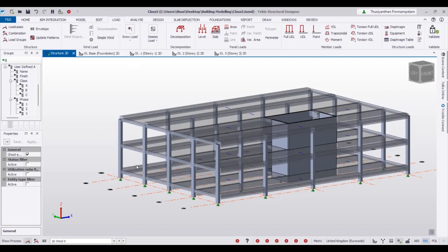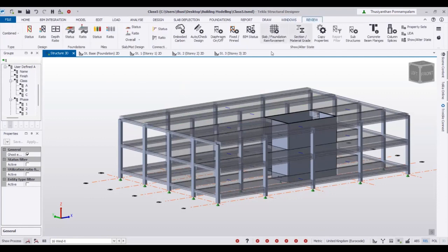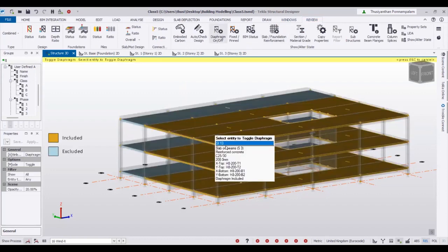What is working is, normally they take this width. Okay, this is the overall width. We are going to apply the wind load. So what they do is they apply the wind load at the center of this building. Then it's distributed, right? So in order to understand this one, you have to understand the diaphragm, how the diaphragm is working, right? Diaphragm.